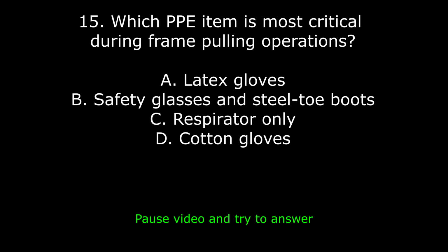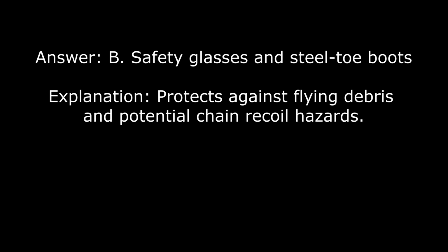15. Which PPE item is most critical during frame pulling operations? A. Latex gloves. B. Safety glasses and steel-toe boots. C. Respirator only. D. Cotton gloves. Answer: B. Safety glasses and steel-toe boots. Explanation: protects against flying debris and potential chain recoil hazards.